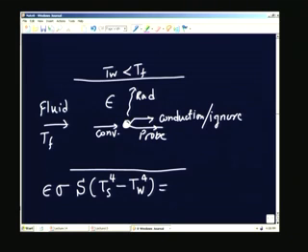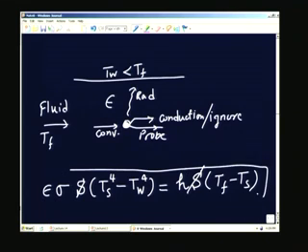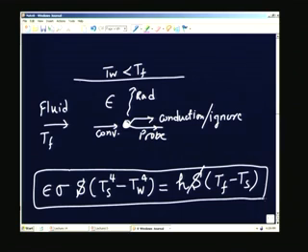This must be equal to the heat transfer coefficient by convection multiplied by the area of surface, which is again equal to S, multiplied by Tf minus Ts, and this S will cancel off, and you see that the temperature of the sensor is now going to be governed by this expression. So, the sensor temperature is given by this expression.